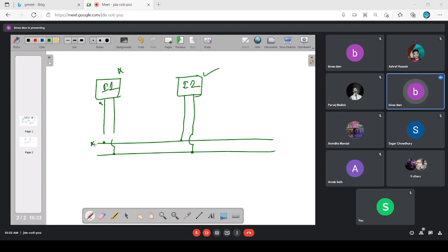So now we have to ensure that if the output of one particular TTL gate is supposed to be disabled or electrically isolated from the external world, it should pose infinite impedance to the external world.